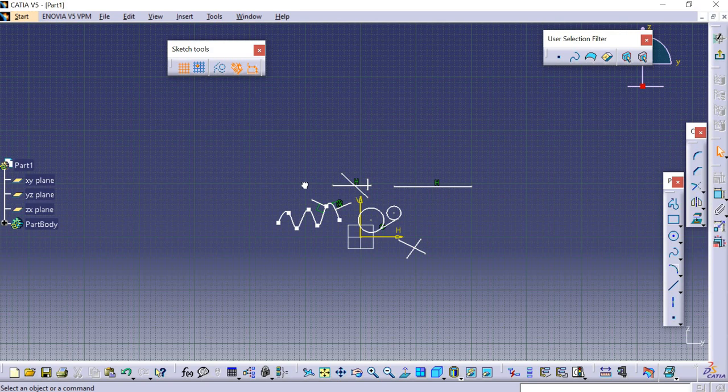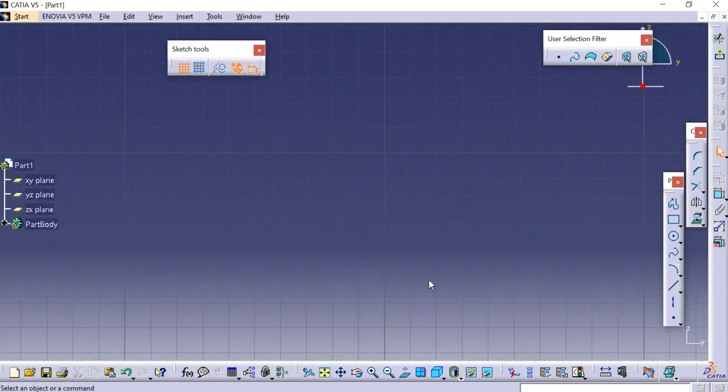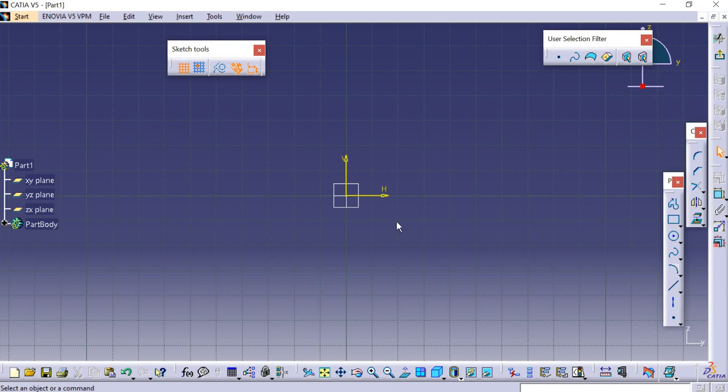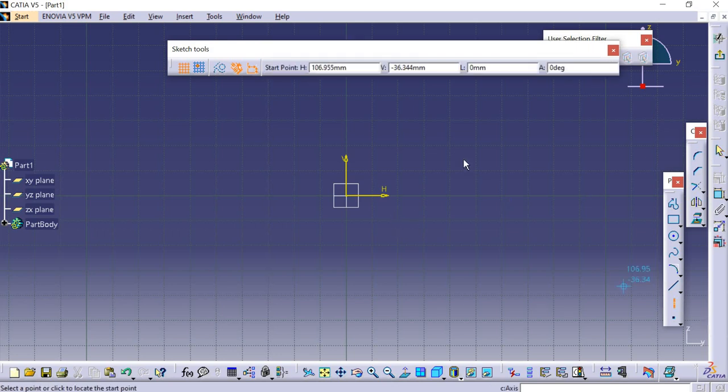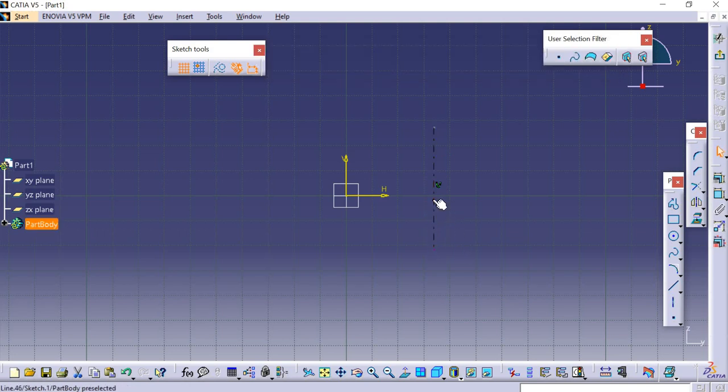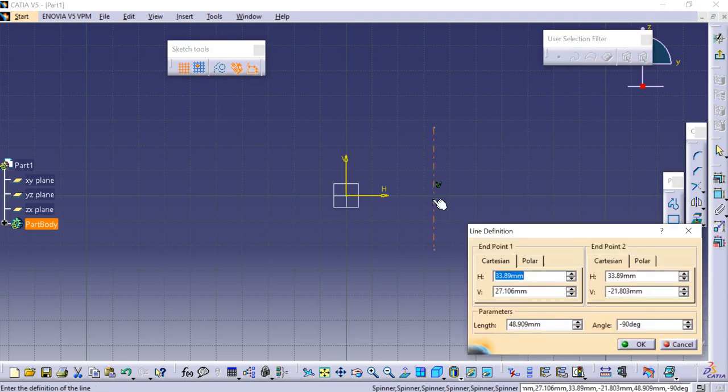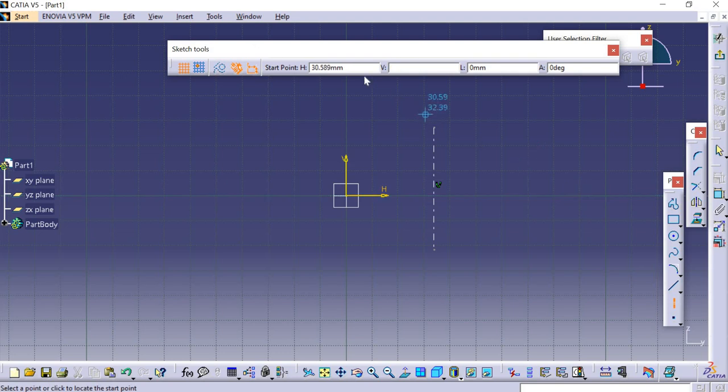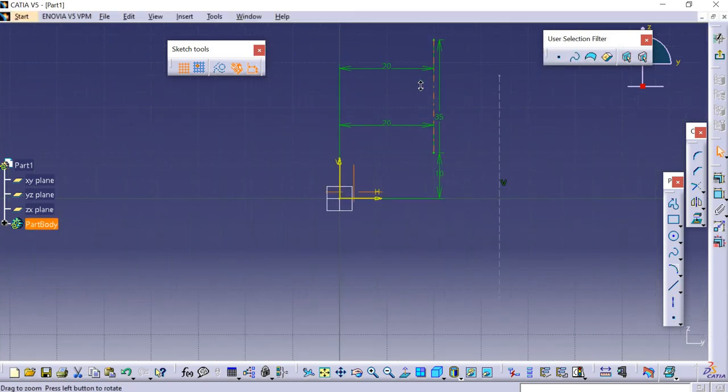Now to creating an axis. So axis is usually needed when we are creating a shaft or groove. It's almost like a line, but it is dotted, which acts as a reference plane. We can change the horizontal and vertical direction here and the length of the axis. Or we can also enter it in the parameter like 20, 35 and the end point being 20, 10. So this is the axis that we have got.